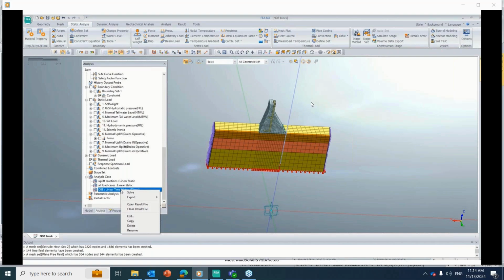And then they found, even then the sections are coming out to be quite large. For a dam, they considered an importance factor of 3, because its failure would be catastrophic. The entire city can wash out because of the failure of the dam. For buildings, it can be fatal for some people, so 1.5 for certain buildings. For one where the loss of life is not there, maybe an importance factor of 1. Even then, the sections were uneconomical.